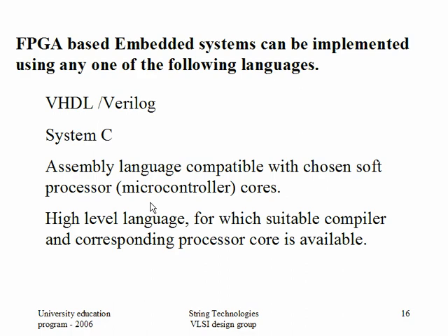Exactly. Hard processor means it is already implemented in the chip, at the silicon level, at the layout level. Got the point or not? Generally we don't talk about hard processor and soft processor in the context of microprocessors, because in the case of a microprocessor everything is hard. There is nothing like soft, isn't it? But in the case of FPGAs, we do use these two words. When you say hard processor or hard core on an FPGA, what you mean is the processor is implemented at the silicon level, available like your general purpose processor, as a part somewhere in the FPGA.